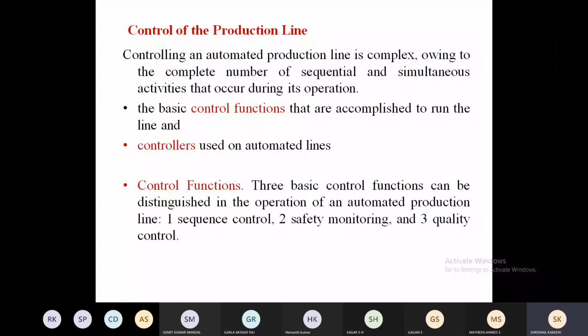Along with this, there will be some kind of uppenders and downenders. These will be orienting and reorienting the parts onto the line, onto the machines, as they go for assembly or some kind of processing. And another thing, there will be some kind of electrical and electronic devices. The electrical device may be a stepper motor. For one pulse, it will rotate by a fixed advance. That means for each rotation, the distance of movement of the conveyor will be limited, or constant.